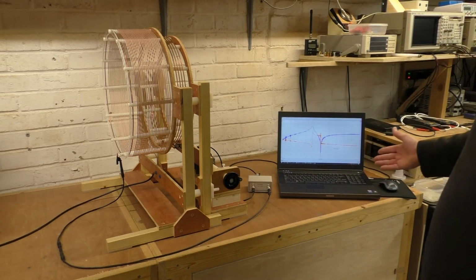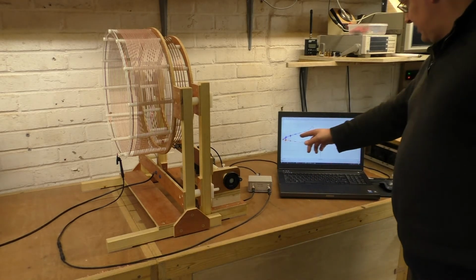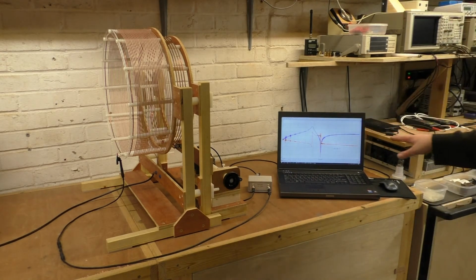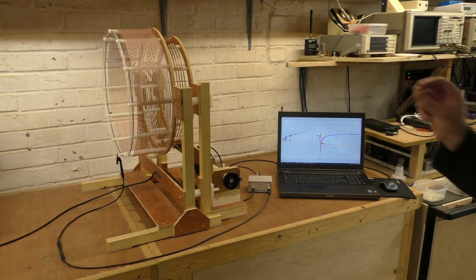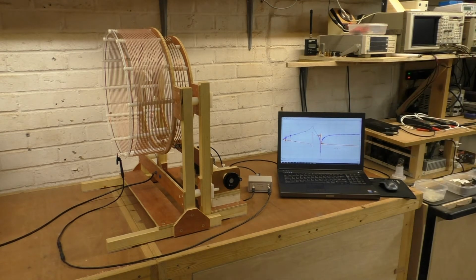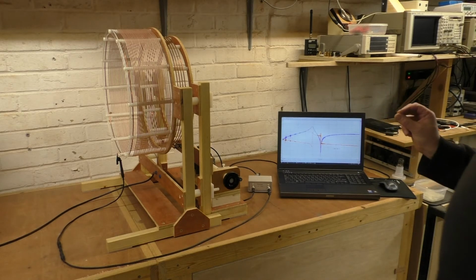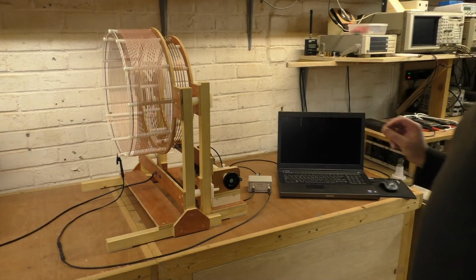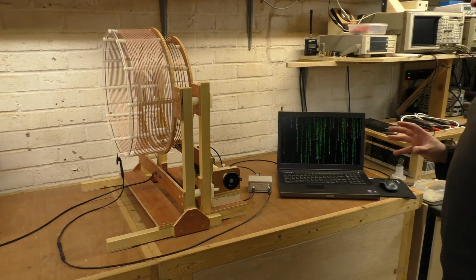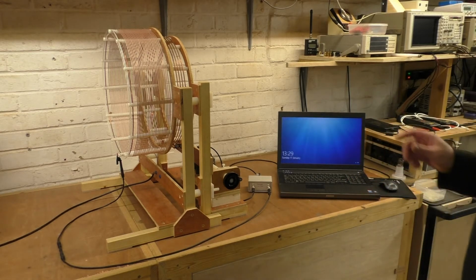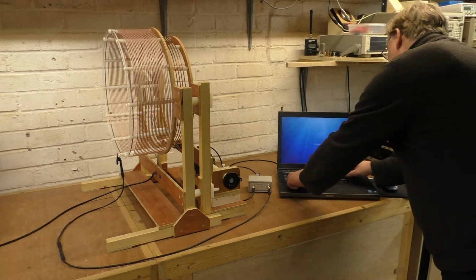With this in the circuit, we can see the characteristic here, where the peak of the resonance is basically just less than 0 dB. So there's a small insertion loss at the resonant frequency. It's not very high, it's a few decibels. But overall, no power gain in this system.